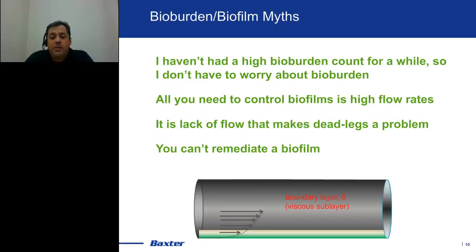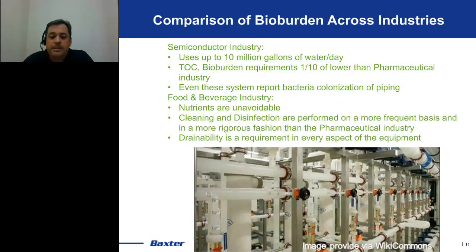And lastly here is that you can't remediate a biofilm. Now that's not to say biofilms aren't extremely difficult to remediate. They can certainly pose a significant challenge. However, they in most cases can be remediated. What I tend to see is that a lot of times when they can't be remediated, it's because either the source or sources of the biofilm can't be identified, or there is potentially a design flaw in a particular piece of equipment. So those type of issues may make it very difficult to remediate a biofilm. You might have to change out equipment or continue an investigation to identify where the problem really is.